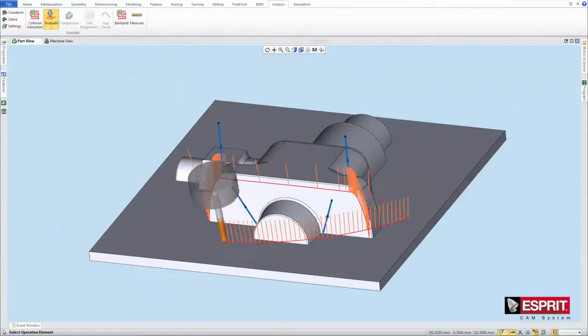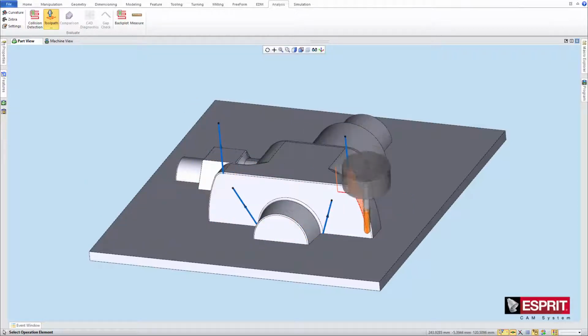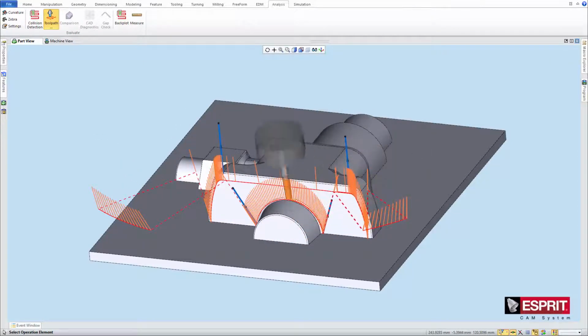Analysis of the resulting toolpath shows that the tool axis orientation changes to match the vector chain nearest to the tool position along the toolpath. The 3D distance from the previous and next vector chain along the toolpath defines the amount of influence that each chain has on the tool axis orientation.